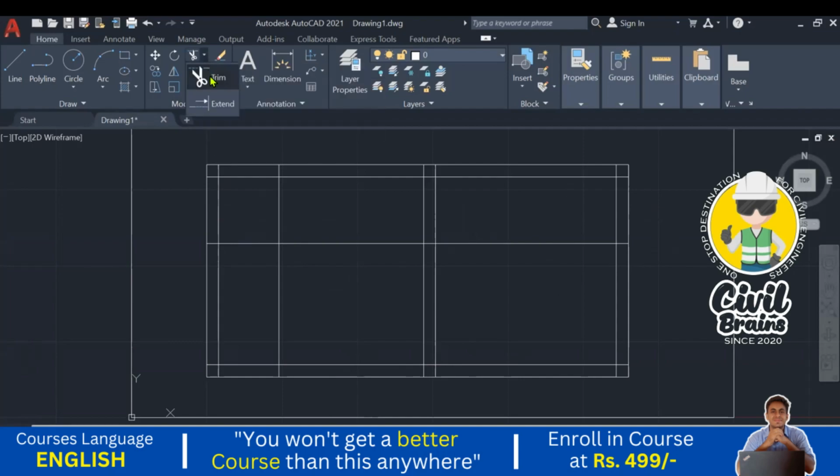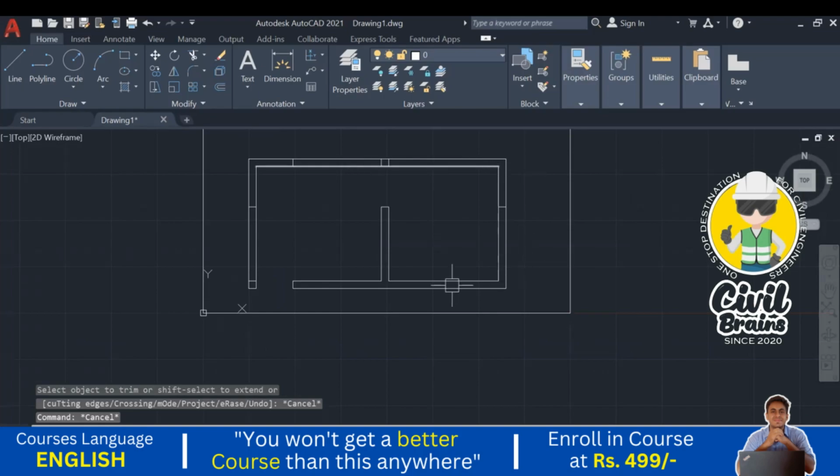We just go to the trim command. I press on the trim command, press enter, and I just trim this one, this one, this one, whatever the extra parts are. Here in the corners also we need to delete this one. Why? While showing the plans, it should look like a whole single plan. Whatever walls are there should look like continuous walls.